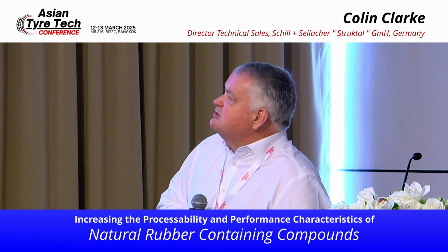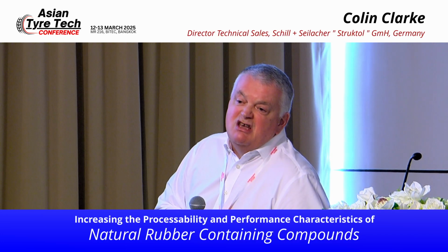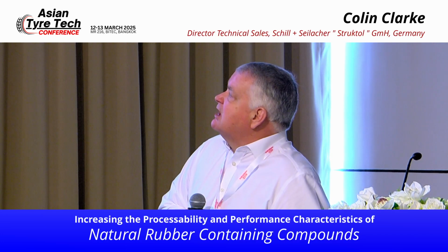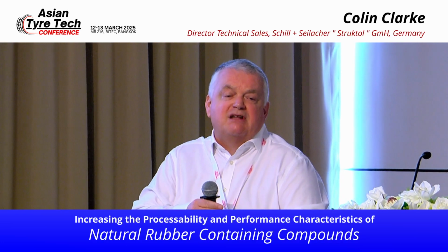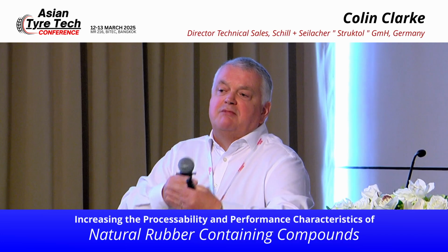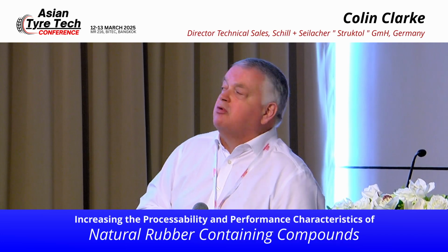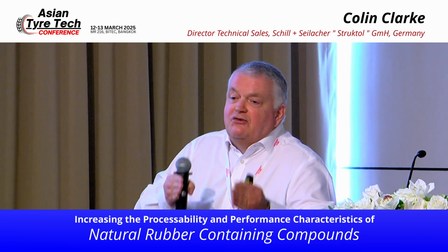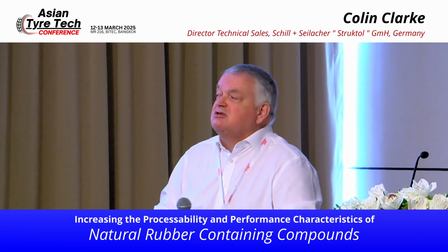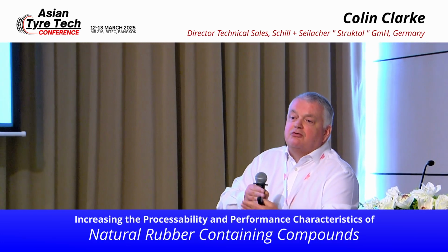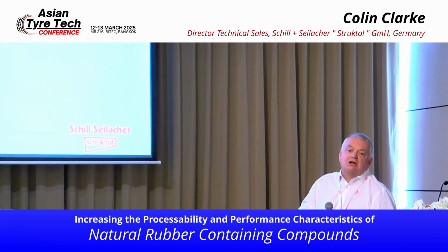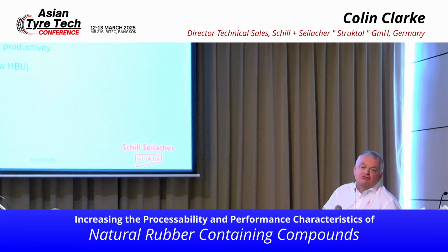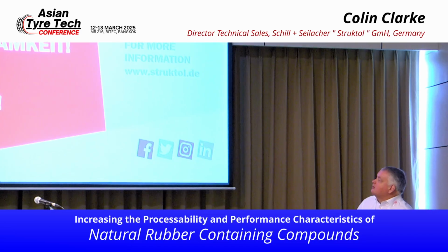So actually I would say for this product we can reduce viscosity at least as efficiently as we can with conventional peptizers. We can certainly offer you the potential to have a step cut. You don't need to do pre-mastication, you don't need to do rubber breakdown. So this is an efficiency saving, this is an improvement in processability, you can improve your extrusion efficiency, and of course you can lower the heat buildup in your tyre. So this is really a win-win situation, if you like.